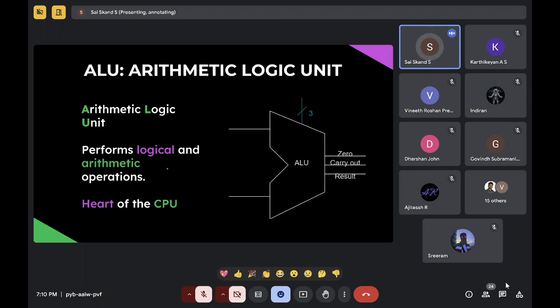So this is the main agenda. This is what we are going to do patiently in Verilog today. How do we design this? We have kept just two flags, 0 and carry out. Why don't we have other flags right now? As in, for this ALU implementation, we are considering only 2 flags.